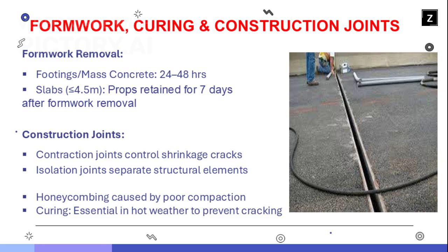Construction joints allow for scheduled halts in concrete pours. They're planned in advance to prevent weak planes in structural load paths. In Dubai's hot climate, curing is critical to avoid rapid moisture loss and plastic shrinkage cracks. Always cure slabs and columns using water or curing compounds. Honeycombing is another common issue caused by poor compaction or insufficient vibration, leading to visible voids in the concrete.